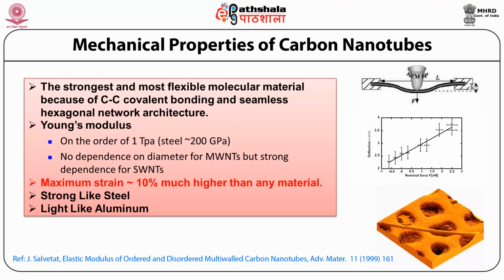Thus, the Young modulus of MWCNT is higher than SWNT, typically 1.1 to 1.3 terapascal, as determined experimentally and theoretically. On the other hand, when many SWNTs are held together in a bundle or a rope, the weak van der Waals forces introduce strong shearing among the packed SWNTs. This does not increase but decreases the Young modulus. It is shown experimentally that the Young modulus decreases from 1 terapascal to 100 gigapascal when the diameter of the SWNT bundle increases from 3 nanometer, about 10 SWNTs, to 20 nanometer.